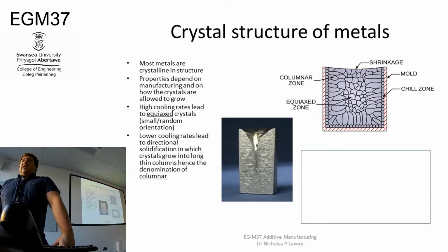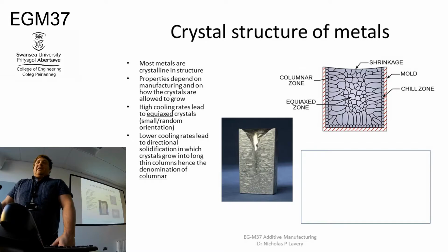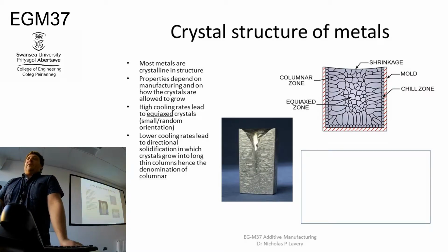You can see quite clearly the defect when you try casting a cylinder, which has got to be one of the hardest things to actually cast, which is funny. You can see the piping where you've got shrinkage coming down the middle of it, but you can also see the orientation of some of the crystals of the metal as they've grown away from the boundaries of the casting.